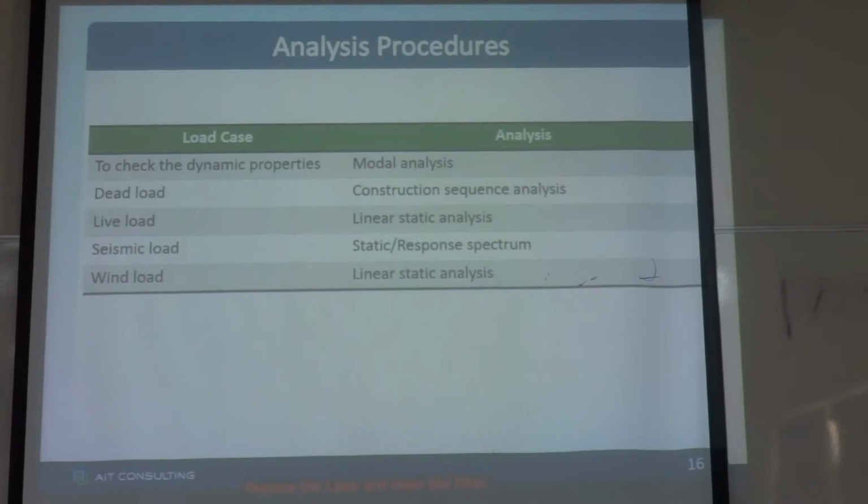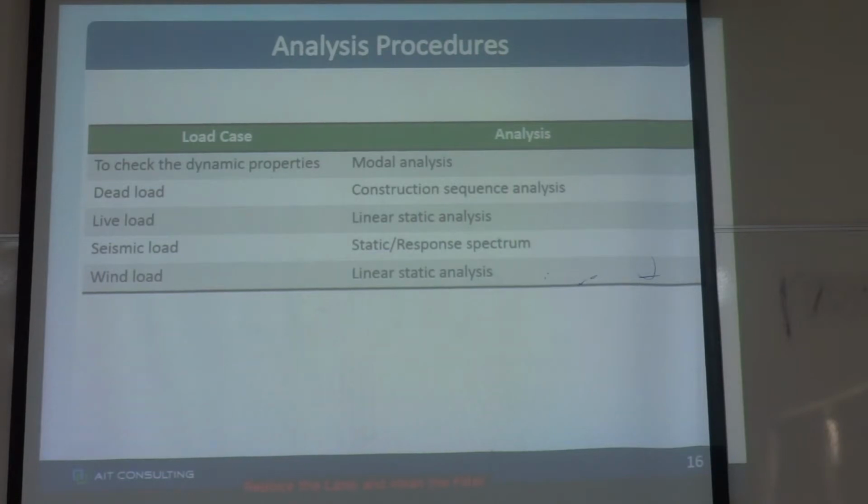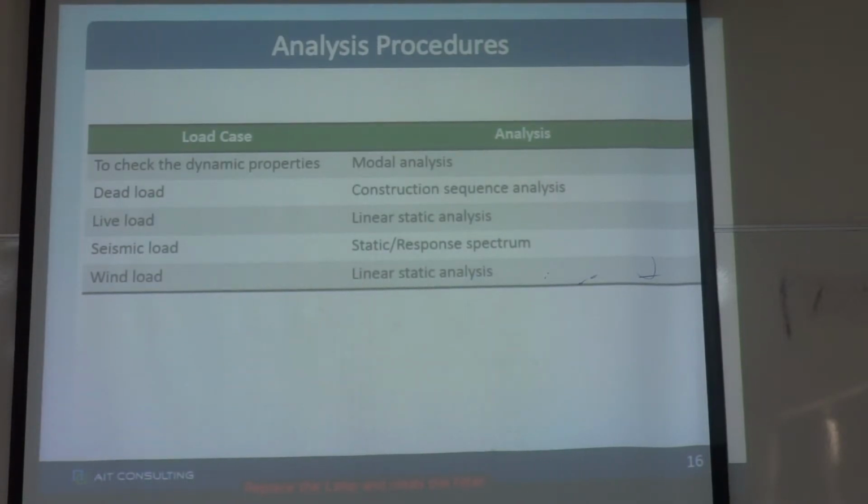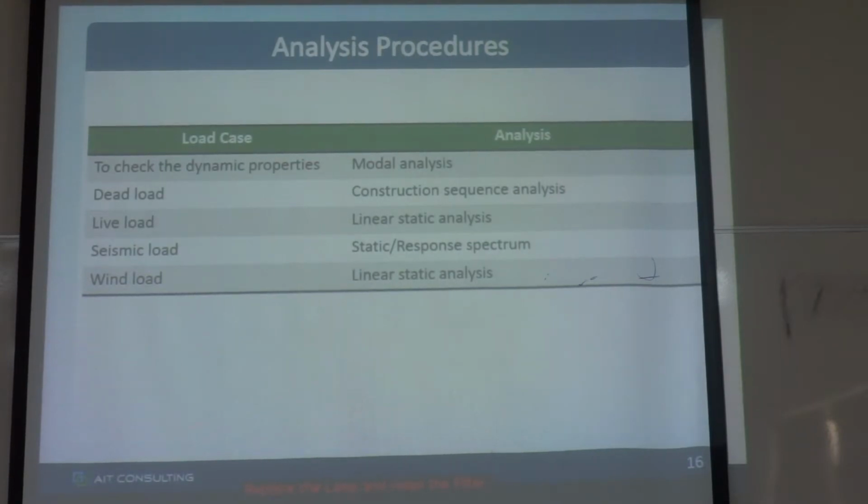After the construction of one floor at the construction site, the engineers will level the columns and the shear wall at the same level, and then continue to another story. So the program analyzes according to that sequence. But if you use normal linear analysis, the program will analyze the entire building at one time, and then it will give you large differential shortening between the members.